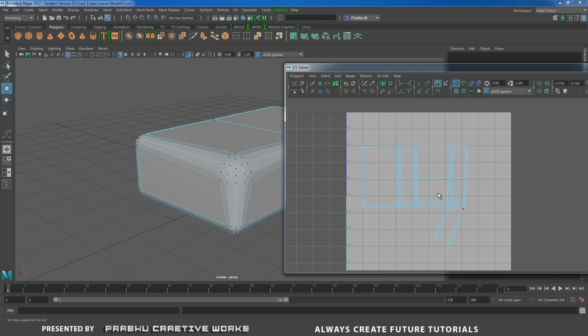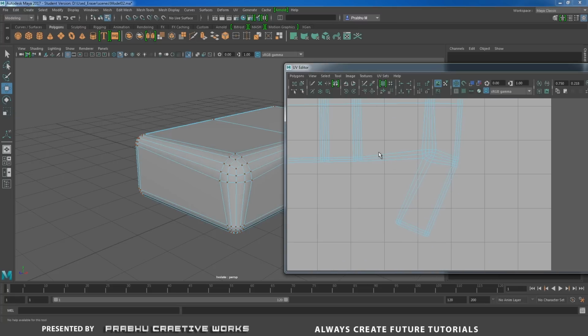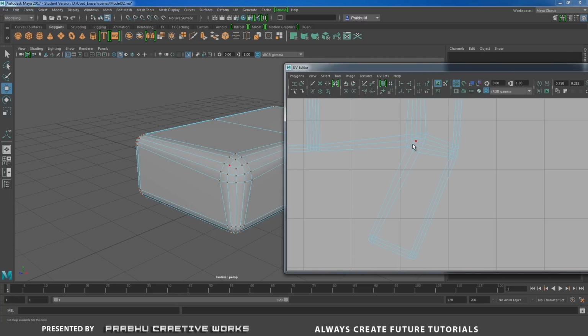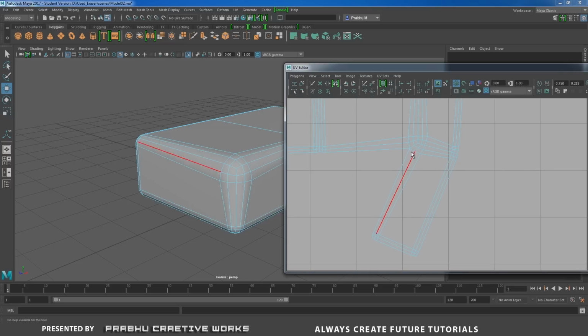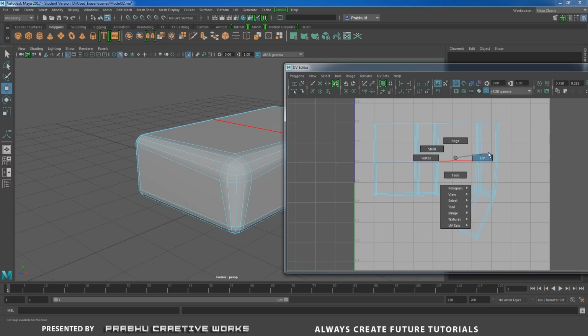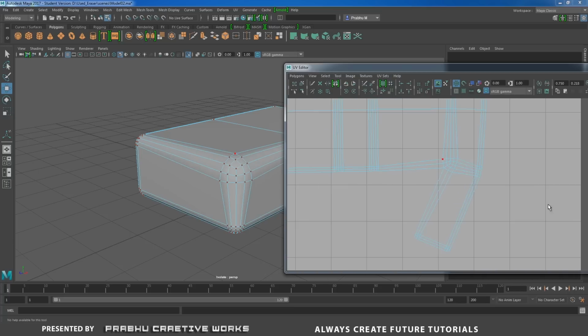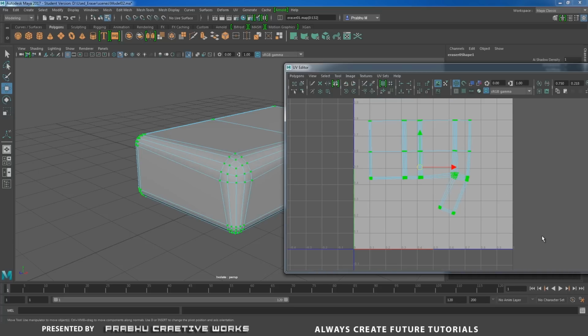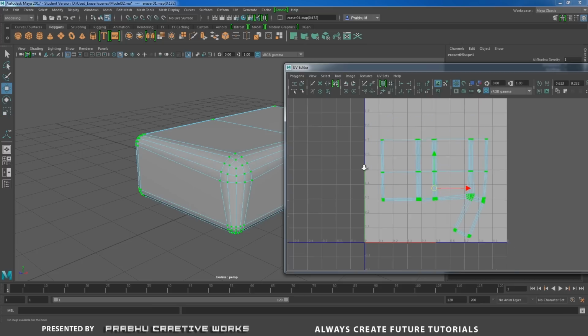It will be a little bit crossed because we did not cut this edge over here, but in this project you don't select these two edges, otherwise it will show up, and you will have to texture in manual. So I keep it default. I will select this UV, press R and scale a little bit bigger, and move over here.